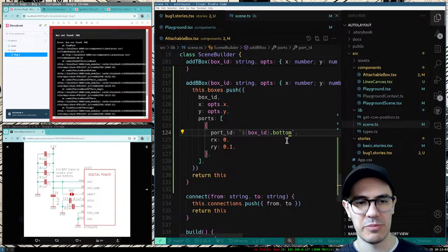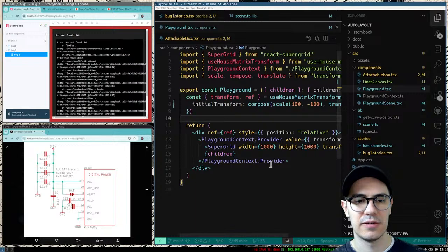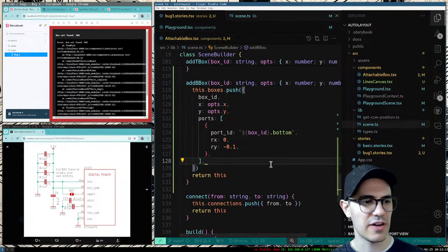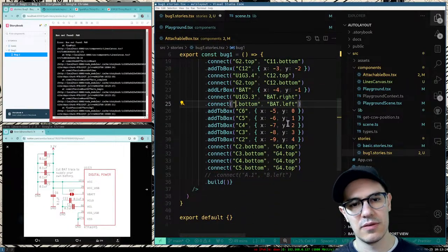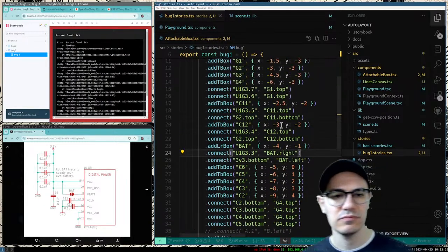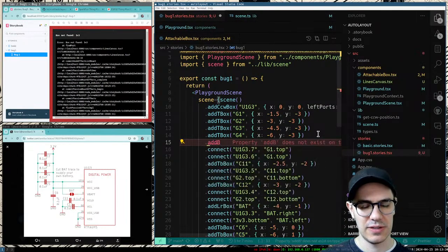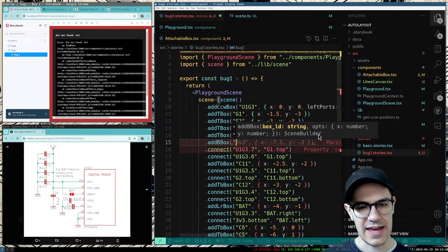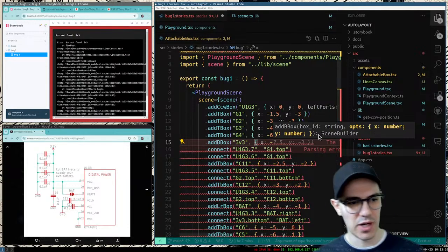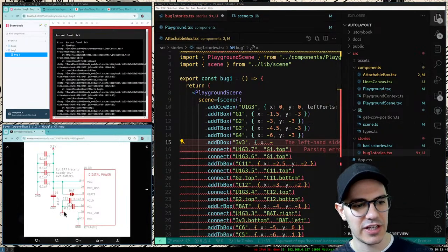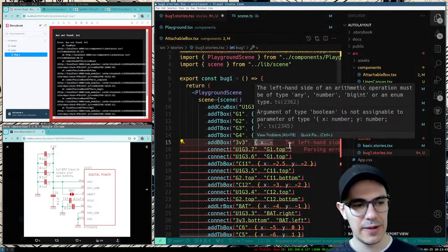Okay, this is going to be bottom for a bottom box, and then the Y is going to be negated. And then we'll add our power. It's not called power here, it's called 3.3 volts, so maybe we'll be consistent with the name. 3v3. So my hunch is that you add a bunch of virtual ones and any component can go down to these, and you add them in and they're part of the layout engine, whether it goes up or down.